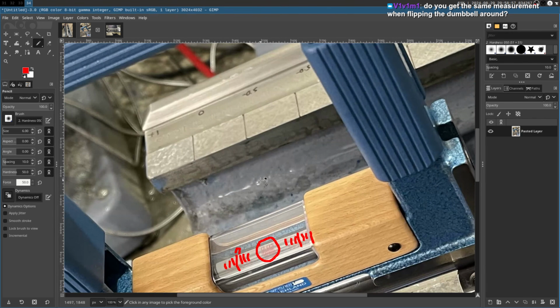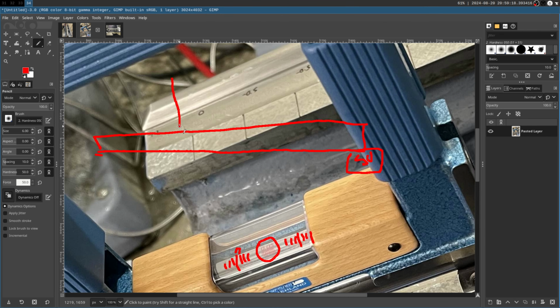So that effectively means that if I had a perfectly flat straight edge resting on a surface, and I add a 50 micrometer coin under there, and this is a 1 meter long bar, and then I set the level on top of this, this would read the bubble 1 division over, right? So that is quite sensitive if you think about what that is in degrees, 50 micron in an entire meter.